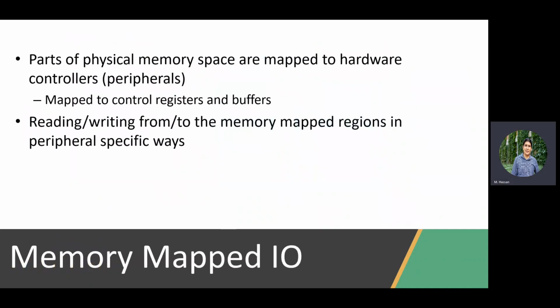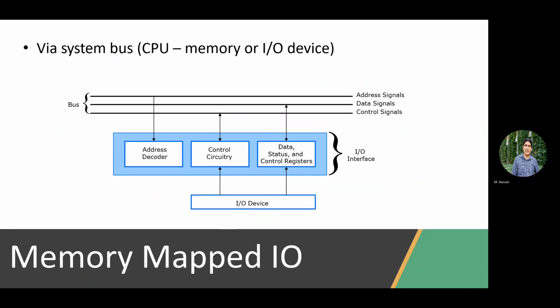So we mentioned that serial protocols are very common in external because of the problems we mentioned, the speed, etc. But if synchronization and distortion is the largest problem for parallel protocols for external buses, this problem is less severe for internal buses because inside the chip, you have better control, you run in a much smaller area, and also you can run in much higher speed. So in that case, synchronization, because you can drive only one clock tree, synchronization is much easier.